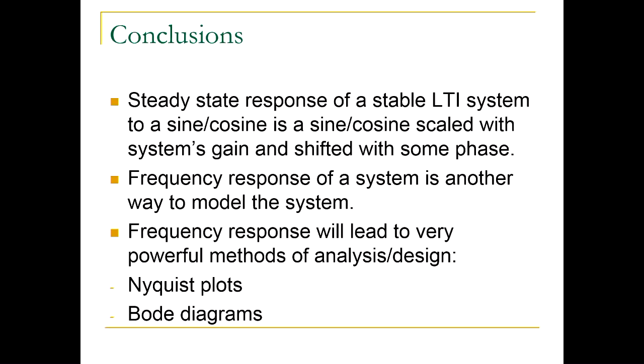We get a differential equation. Then we learned by Laplace transform how to obtain the transfer function. But now frequency response is just a different way to write a model. It contains all the information about your system, everything about your system, right? And we will then, in the rest of the subject, talk about Nyquist plots and Bode plots, which are really cool analysis and design tools. We will use them a lot for the rest of the subject.